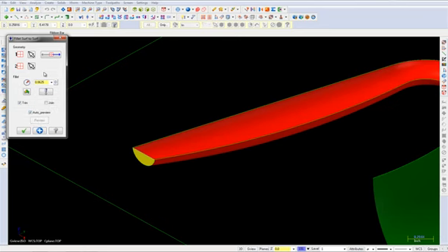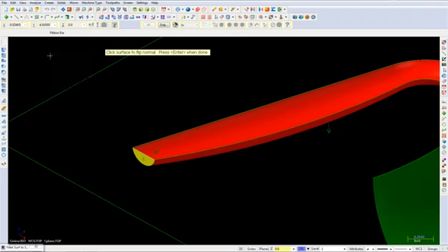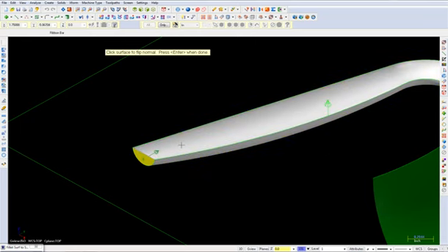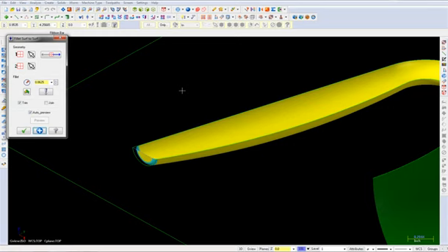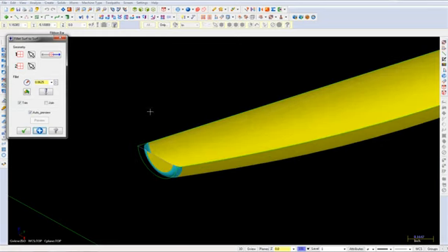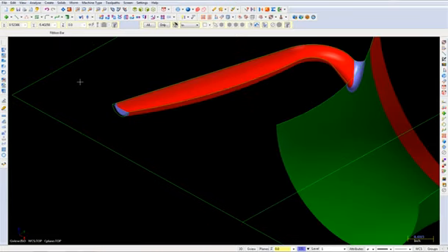Mastercam may tell you no fillets have been found. Click on the Flip Normals button. Make sure that both normal arrows are pointing inwards towards each other. Then press Enter once complete. The fillet should appear as shown. Select the OK button once complete.